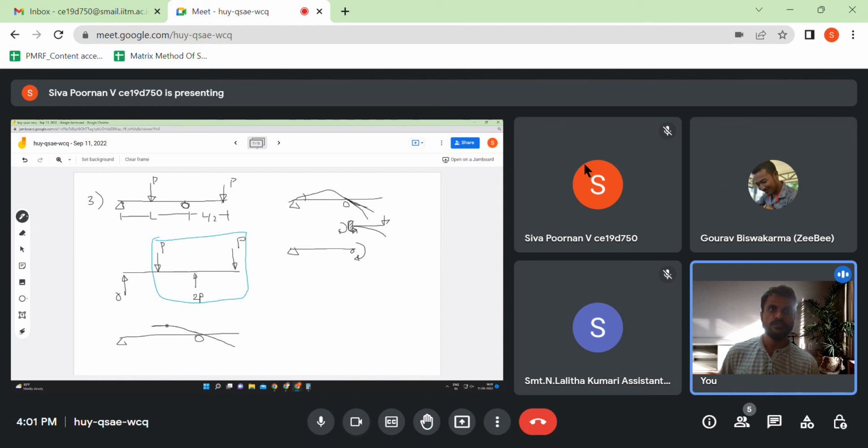That much we know. So this total portion should look like an upward simply supported beam. It should have similar curvature, like a simply supported beam. So it will be something like this. Just like if you have a simply supported beam with an axial force, this curvature, this bow, should be the same as this bow. Only thing is that it is just put in a tilted format at this point. That's the only difference.